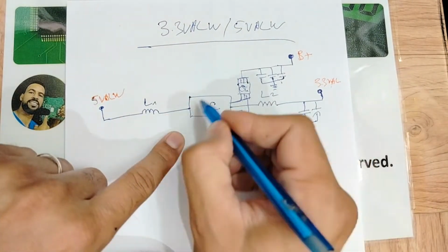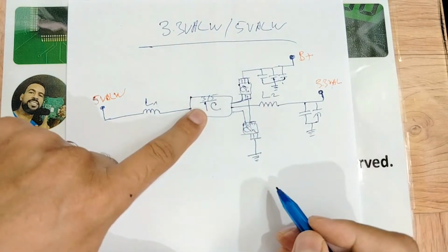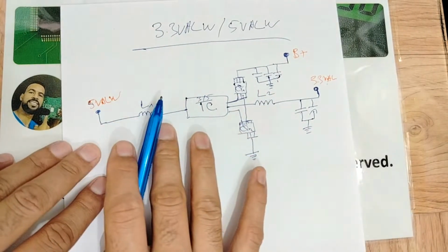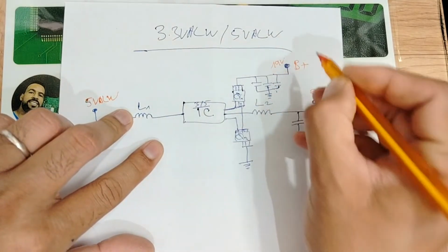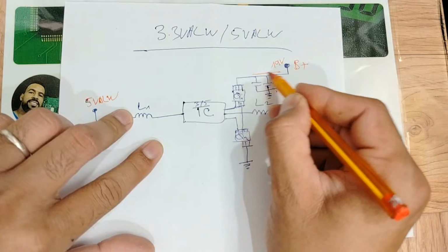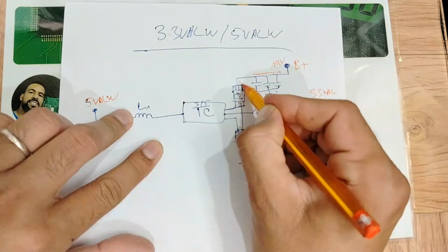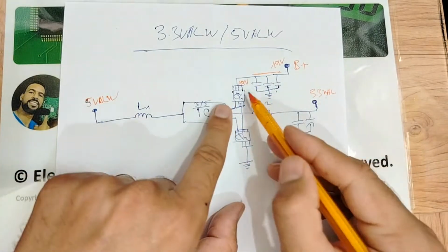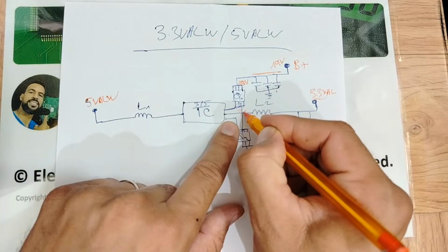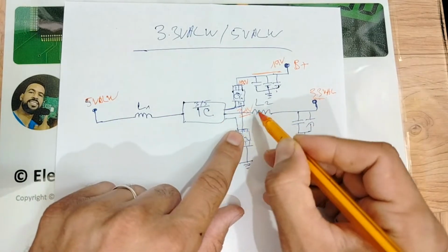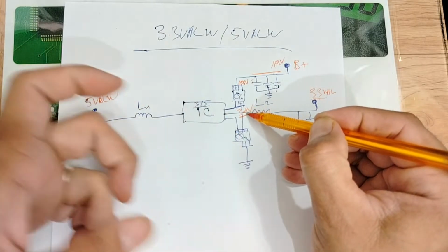We call it the 3-volt, 5-volt control IC. Okay, so here, my friend, the B plus, basically 19 volts, will pass through this ceramic capacitor in order to be filtered, and then will be present here at the MOSFET. So here 19 volts, and here my friend we will get 3.3 volts. Why here do we have 19 volts and here we will get 3.3 volts?